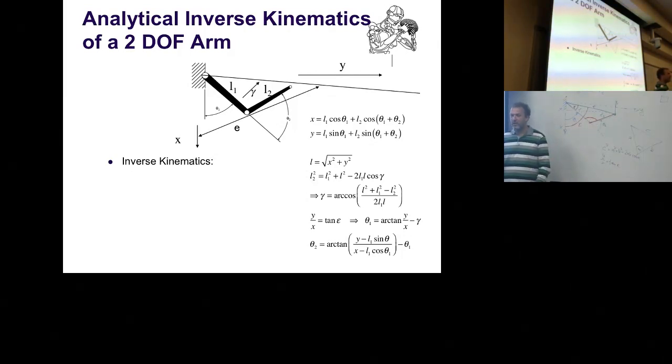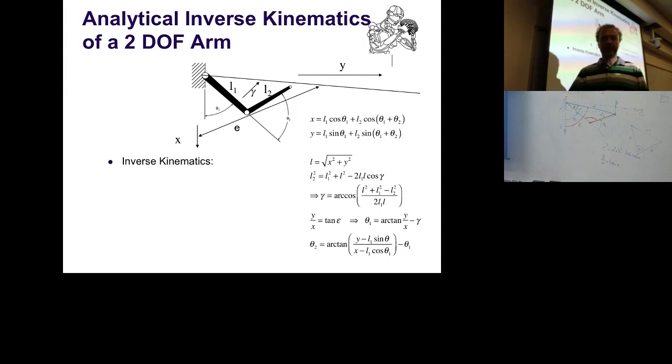There are many ways to do this. It's all about triangle geometry. Good. So that was relatively straightforward, and obviously it's a super simple triangle. This is as simple as it gets. Now, imagine you do this in a 3D space. You're basically all the time imagining yourself wandering around the robot and trying to figure out how it's configured. It's a huge pain. And frequently, you can simply not solve it. You cannot find appropriate triangles which you can solve. And that's when we have to go to iterative solutions.